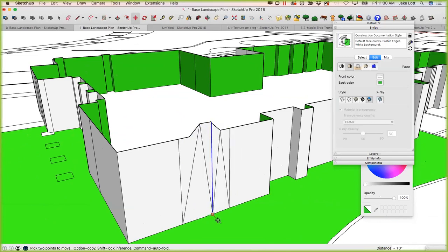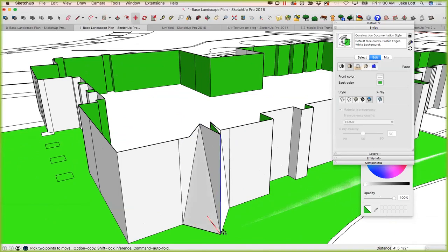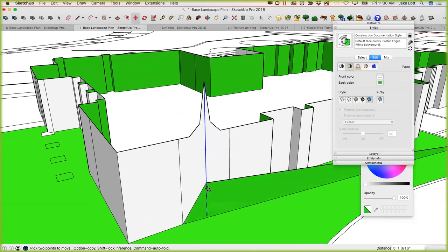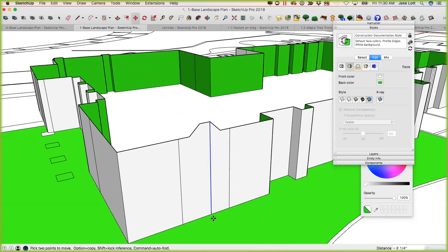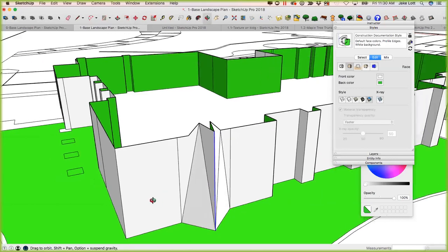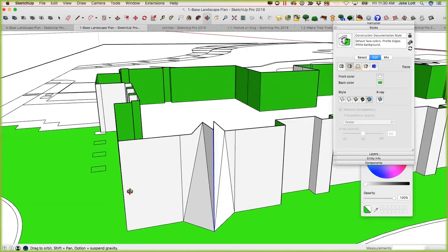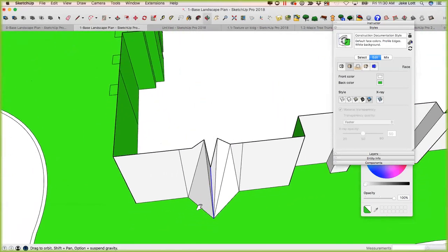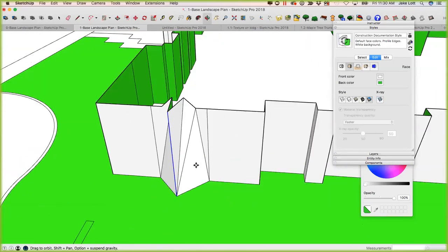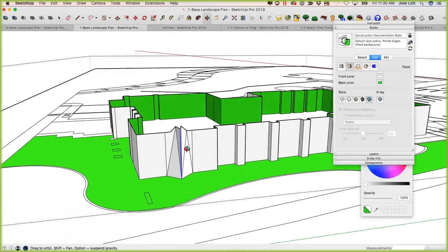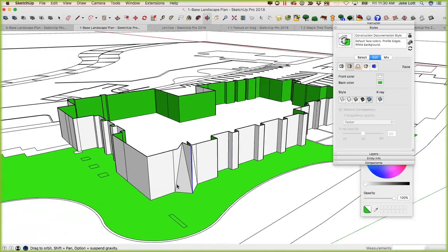I can drop this in here, and again, kind of fun to just play around with, but selecting a line, grabbing the move tool, and dragging it out. Now it's locked on this plane here, and it's glued on to where it is. But if I hit the arrow keys again, I can run it in the red axis, into the green axis, or even into the blue axis, and it locks it that way.